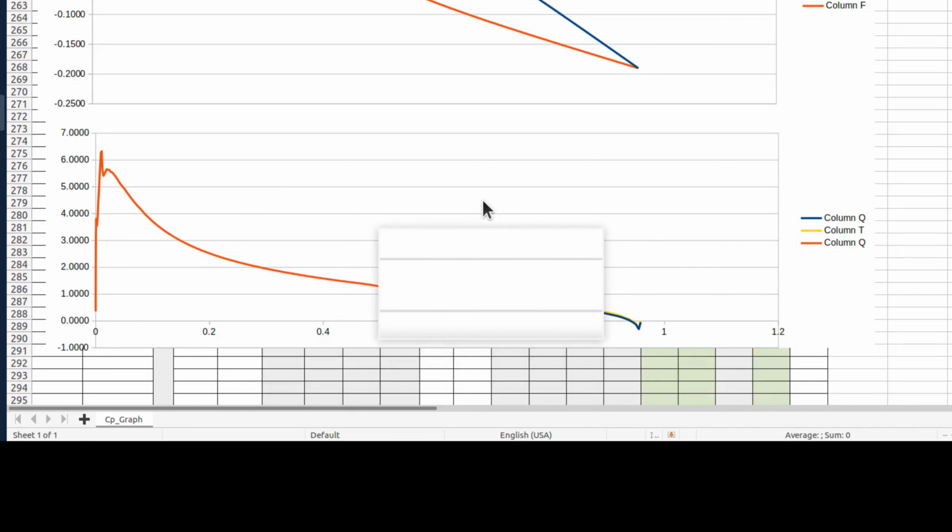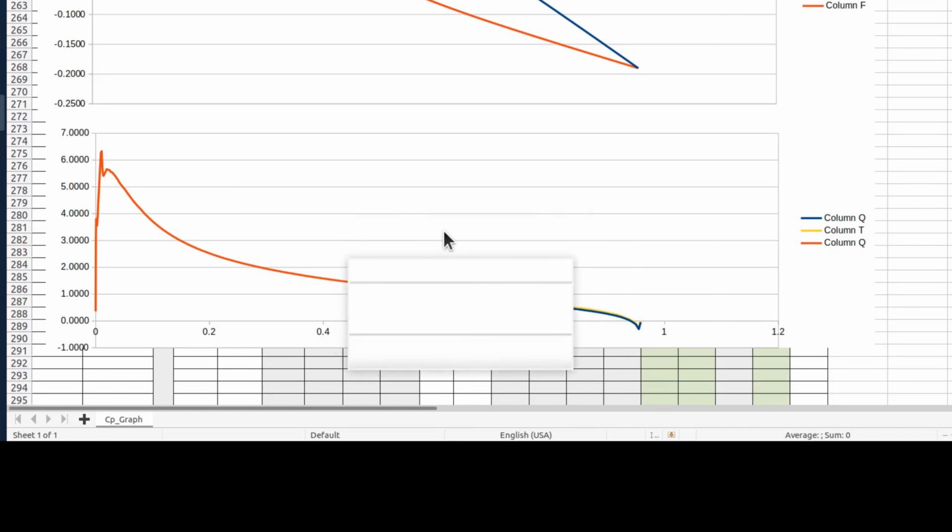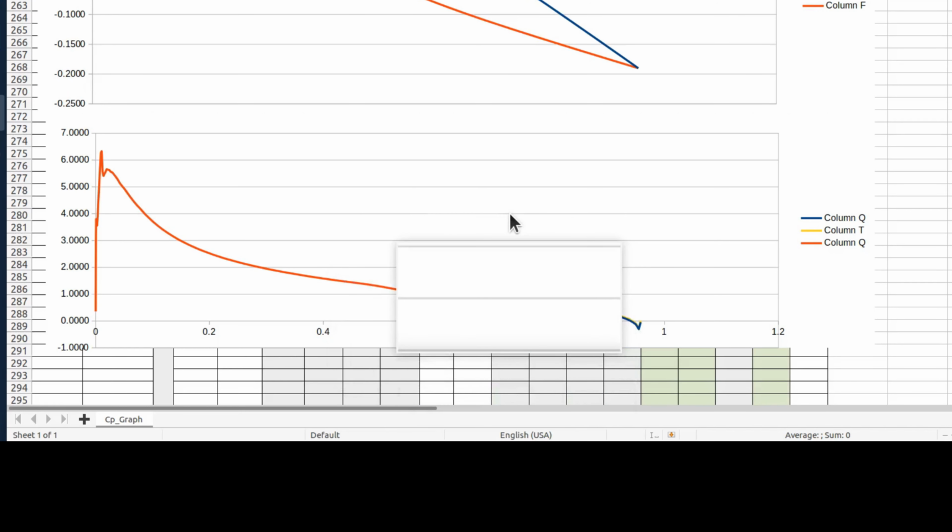All right, now the next thing to calculate is what will be our load per square inch. When we go to start doing static load testing on our tail, we're going to want to be able to put sandbags on it. So I need to know how much load per square inch. And then I can calculate, well, what's the area that the sandbag would take up? And then how many sandbags do I need to load on there to get the right load? So that's the next thing we'll look at.